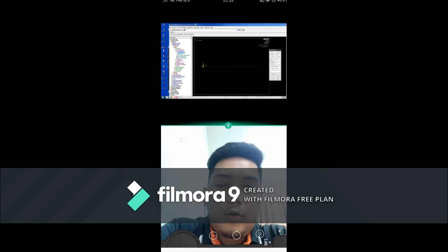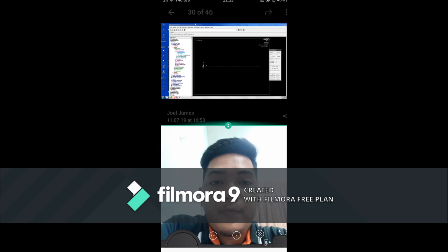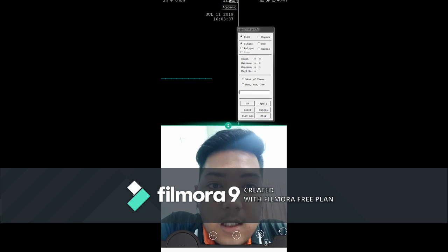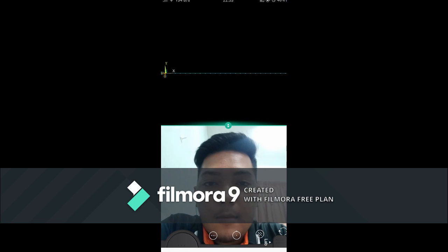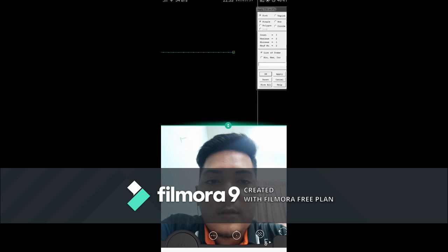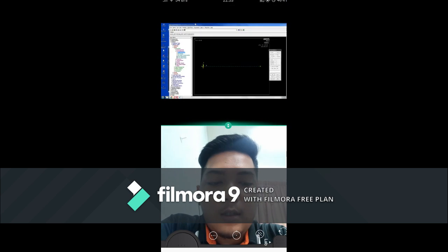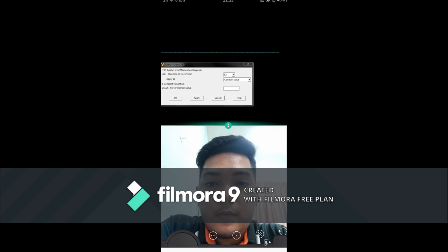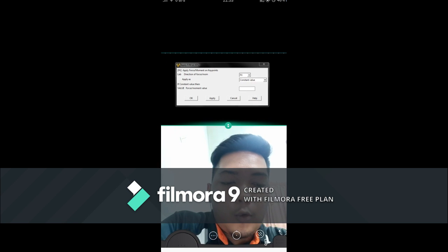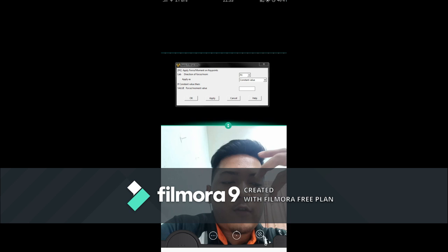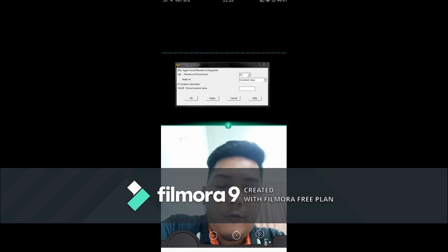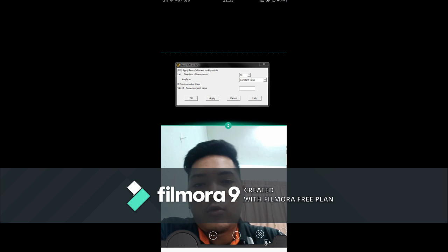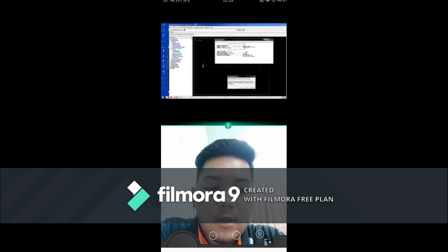And now we proceed with the direction selection, and this is the same thing, pick single and click OK. The repeating step by just clicking on key points, select pick single, and now this is it. We need to apply or choose the direction of the force, and two of the choice is Fx for the x direction and Fy for the Y direction, and we need to choose either one of the direction.